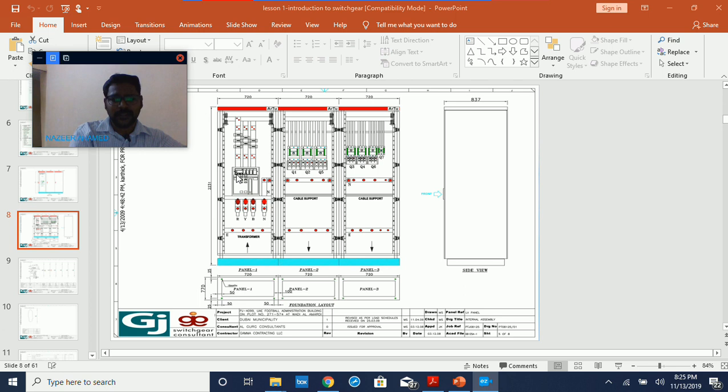Then we discussed the technical characteristics: rated current, Icu breaking capacity, withstand capacity, service capacity, and Icm making capacity, and some other voltage characteristics also: rated voltage, operational voltage, impulse withstand voltage, and insulation voltage. After that we checked the available ampere range with respect to breaking capacity. Like we selected for 1600 amps 3-pole ACB 50 kA, so we went with the E1N16 breaker.